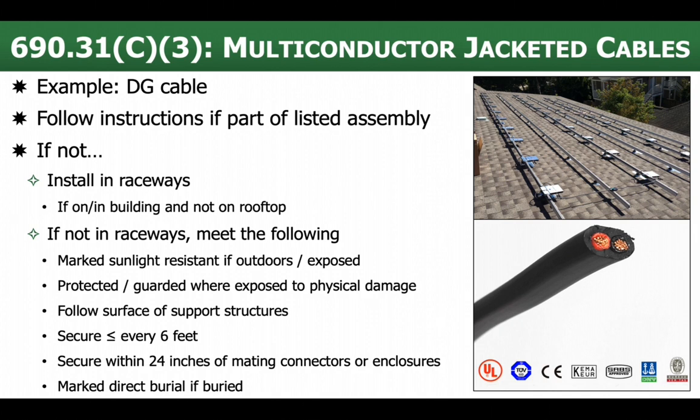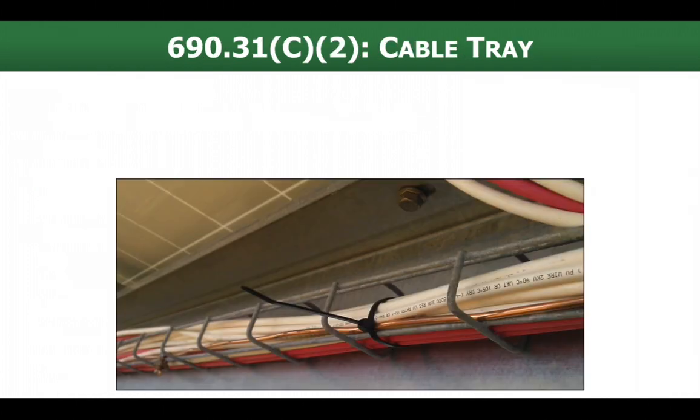Now, if we're not in or on a building and we're not on a rooftop, we're going to be in the ground, right? So if it's going to be buried directly in the earth, not in some kind of raceway, then it's got to be marked direct burial.